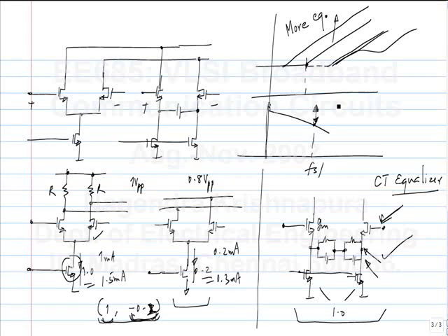If the channel is a first order type of response, then it will compensate it exactly, right? But if it is not, then it will compensate it somewhat approximately. So you choose the equalizer by making the boost of the equalizer equal to the attenuation of the channel. Anything else?